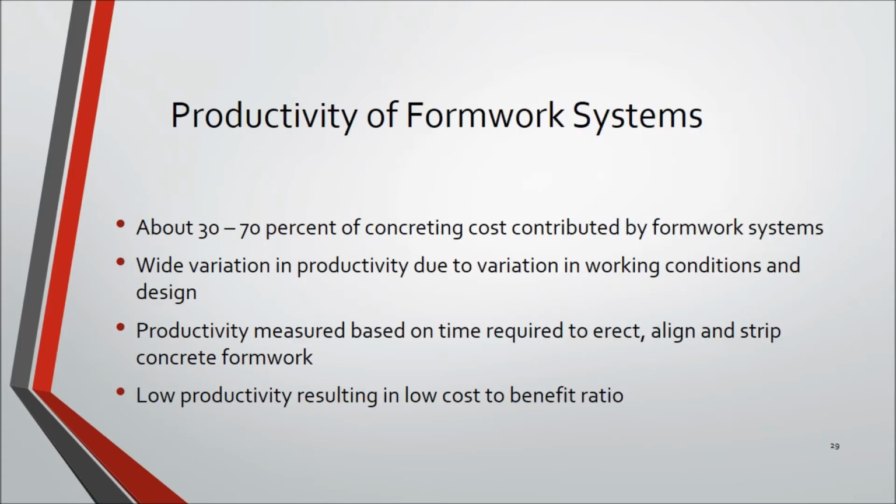After understanding the various types and components of formwork systems, let us now move on to the productivity of these systems. Currently, about 30–70% of concreting cost is contributed by formwork systems. For this, productivity is measured based on time required to erect, align and strip concrete formwork.